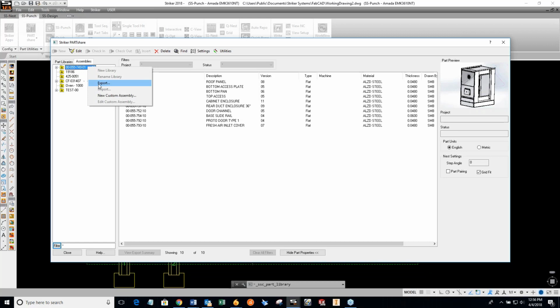And basically they were sending it over to their other software. And what that does is it takes all of the DXF files and copies them to a specific directory, names the DXF file based on the part number and revision, but then it also dumps a little XML tag out there that contains all of the part manufacturing information, so material information and so on, so that somebody could write a script that would just read that information and pass it off to some other CAM software.